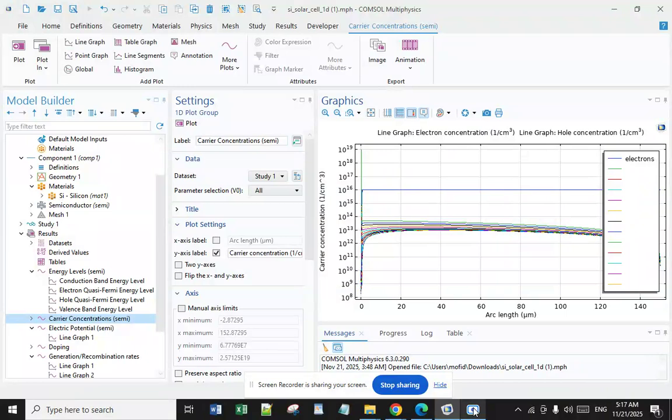Leakage currents in silicon solar cells are undesirable reverse currents that reduce power output by flowing opposite to the photocurrent. They are caused by minority carriers and are sensitive to temperature changes, making them a significant factor in solar cell performance, and a result of damage to the p-n junction. Minimizing leakage current is critical for efficiency and requires careful design and control of manufacturing processes.